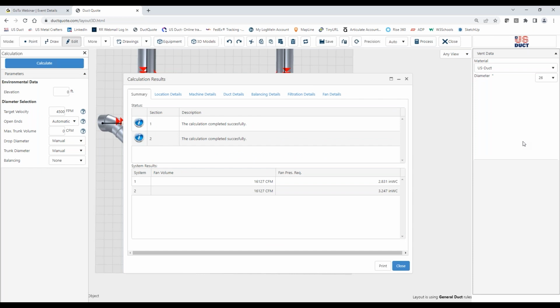All right, so to kind of cover what we have just talked about, fan pressure is important because it has to do with how easy it is to move the air, how hard the fan has to work to move it. Fan works harder, wears out sooner, needs more maintenance, and chews up more energy. Well, how does the trunk routing impact? Well, basically, the straighter the path from whatever to the collector or fan, the better. The more branches is going to equal more fan pressure required. Typically more turns and elbows, same thing, but they are much less of a turbulence causer than branches.